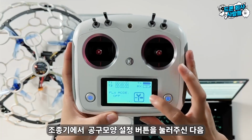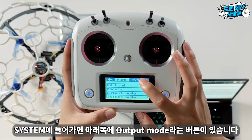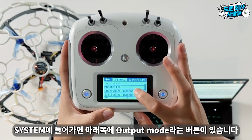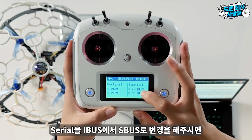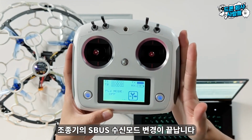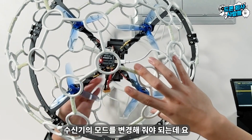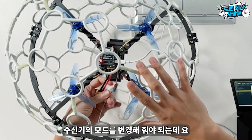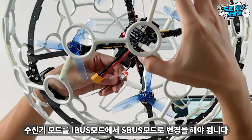Press the tool-shaped menu setting button on the controller, then go into the system section where you will find a button labeled output mode at the bottom. If you go into this button, change the output from I-bus to S-bus, and the S-bus mode for the controller will be completed. Next, we need to change the mode of the receiver from I-bus mode to S-bus mode.